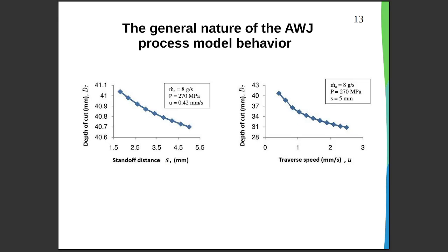Abrasive mass flow and fluid pressure have the greatest influence on AWJ performance. The AWJ process is possible when the pressure of the liquid jet per unit surface area of the cut exceeds the strength limit of the material being processed. All things being equal, a further increase in the pressure of the liquid jet will lead to a potential increase in the thickness of the material cut in one pass. Considering the equation in general, the AWJ model can be presented as follows,